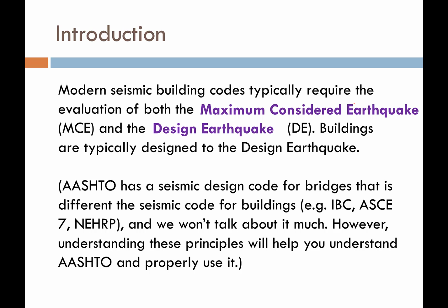And then the design earthquake, or the DE. The design earthquake is the everyday earthquake. It's the earthquake that we're trying to design to keep our building from tipping over. The design earthquake is the earthquake ground motion that the structural engineers will actually use in the majority of the design. But for certain things and certain structures, they might refer to using the MCE ground motion instead.